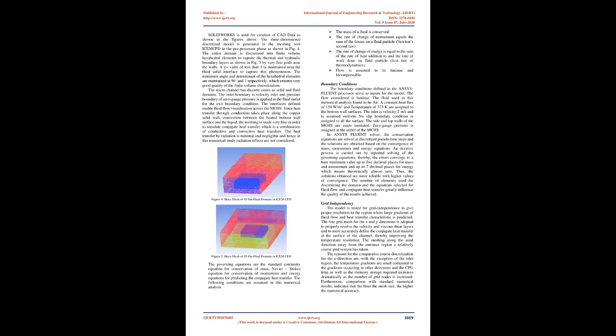Heat dissipation is an unavoidable byproduct of electronic devices and circuits. In general, the temperature of the device or component will depend on the thermal resistance from the component to the environment, and the heat dissipated by the component. To ensure that the component does not overheat, a thermal engineer seeks to find an efficient heat transfer path from the device to the environment.